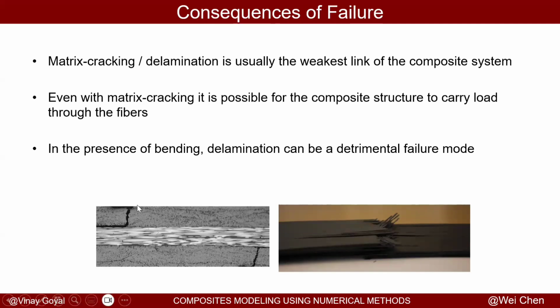As you can see here, there's a resin cracking over here, a vertical crack that turns into a delamination. Here you can see several delamination planes, and in addition, you can see fiber failure.